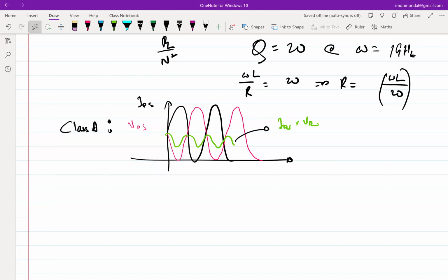One way to think about it is that when I am pushing current into the load, that is inevitable, that is desired. But when I'm drawing current out of the load, that load current is now getting pushed into the MOSFET. So that is not going to the load, but I am giving it an alternate path to go into the MOSFET, and that is also increasing the power dissipation in the MOSFET. Does that make sense? So what if I do not allow that path?